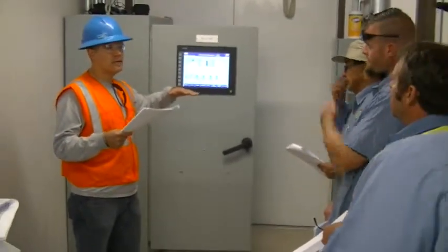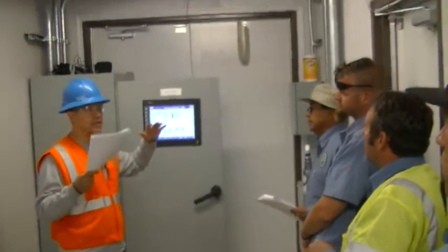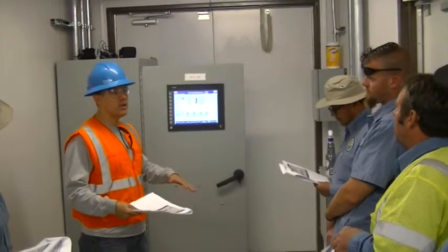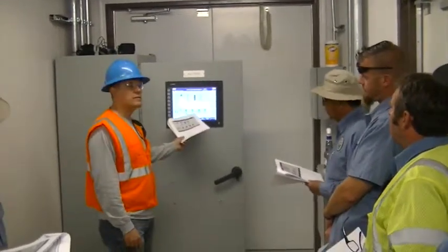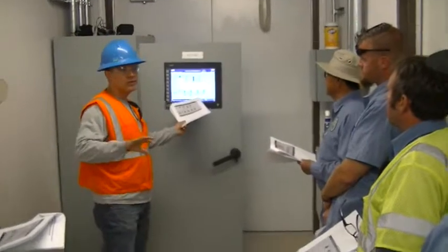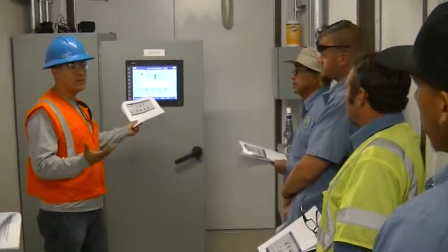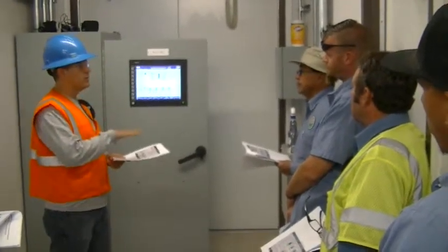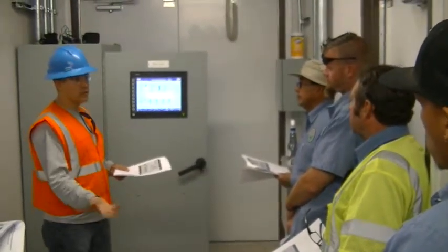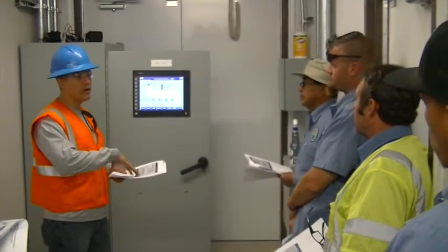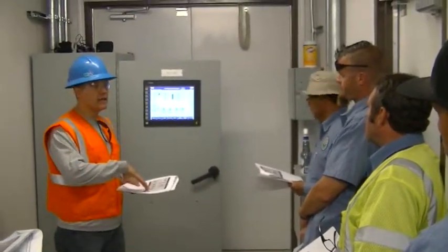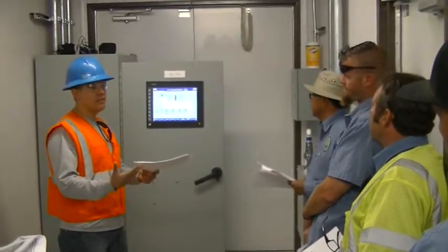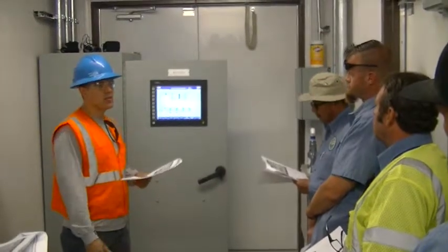Basically, you'll probably get a fault on your drives if the power drops out, until you get your power coming back up. I've got it set up so it will reset if it shows transferring over to generator or transferring back over to main power. After 45 seconds, it'll reset itself to allow everything to come back up normal. If it doesn't at that point, then it's going to be on the Mercoids.